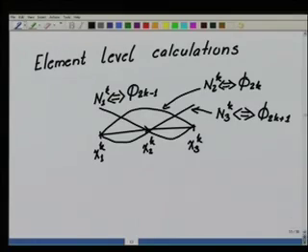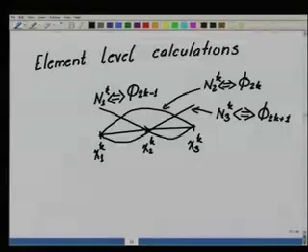Okay? So, what the element is going to contribute to is the 2k minus 1th equation, 2kth equation and 2k plus 1th equation. And which columns of these rows are going to be non-zero? The columns which are going to be non-zero for each of these rows are the 2k minus 1, 2k and 2k plus 1. To these columns only the element is going to contribute. To none of the other columns it is going to contribute.